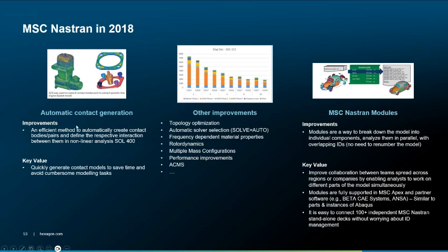Okay, so in 2018, there's an ability added in Nastran to automatically generate contact. So for a simple model where everything needs friction and everything is in contact, you can let Nastran figure out which elements are where, and you can even write out the information in terms of, again, these are my new contact bodies. Okay, so that's, I'd almost say, useful in a small subset of models, because often we have different material types, different friction coefficients, and that is not then possible to set because we don't initially have the bodies. But if it's a quick analysis where everything is the same material and same friction behavior, it's then relatively easy to set. You can also choose additional settings, whether it should be contact or glued contact. So you have a bit of control, but not on a per part kind of a level.